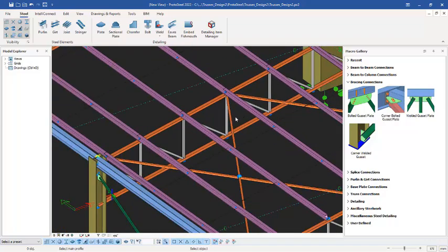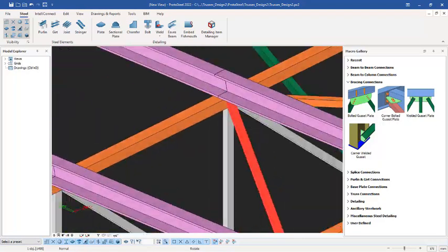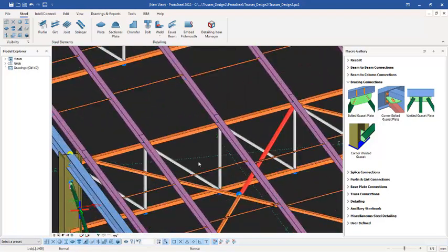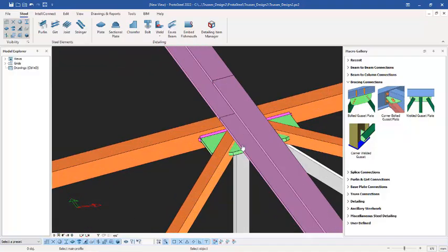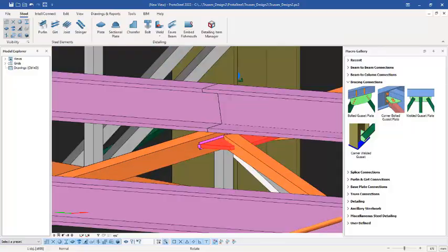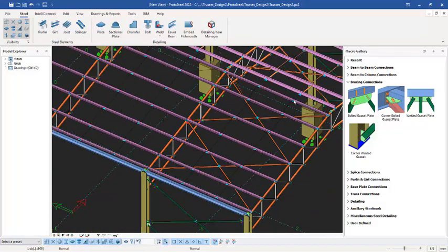The same thing is applicable to this roof brace. If you zoom in closely, it's just the same method you will use. Select this member, select these two just like this, right click to insert that. So you can see the gusset, the way it looks, very neat, it's not clashing with anything. So this is how you fix all your gusset plates successfully.